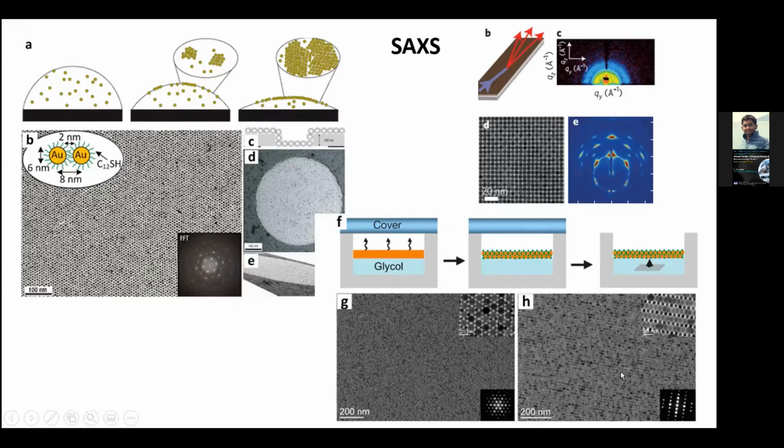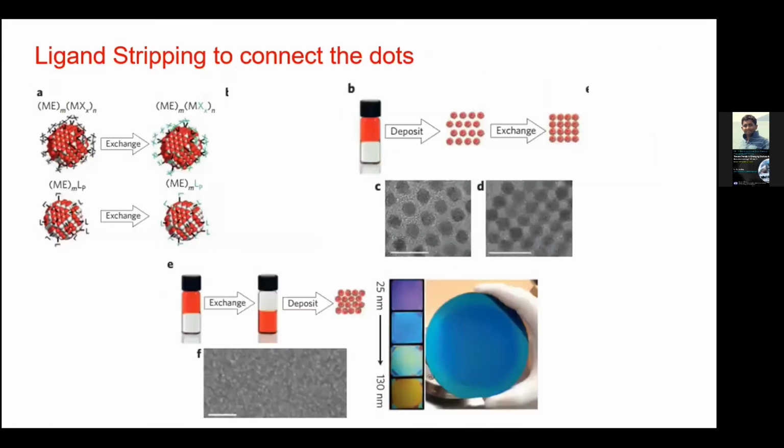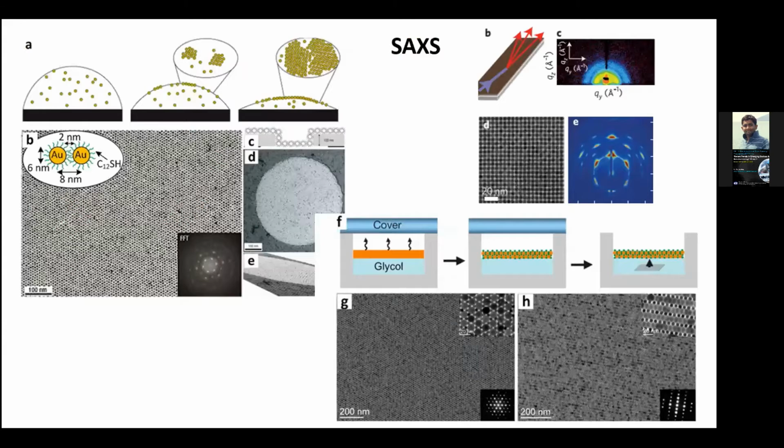In this way we can have a monolayer or bilayer film, which is good for making good devices. As you can see here, there are lots of ligands on the surface. As I told earlier, this ligand is completely non-conducting. You have to remove this ligand in such a way that your nanocrystals stay intact on the surface, that means it forms a monolayer film.